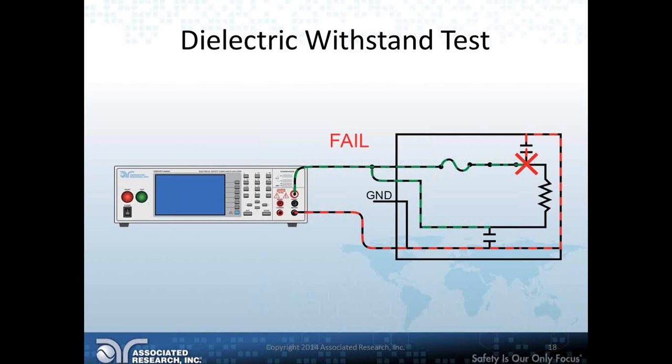When the breakdown occurs, especially for a long period of time, the next gradual application of voltage often causes a breakdown to occur at a lower voltage than initially measured. The best indication of dielectric breakdown is a leakage current measurement significantly higher than the nominal current measurement.